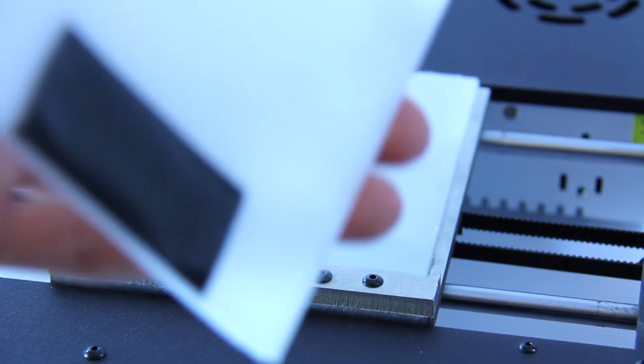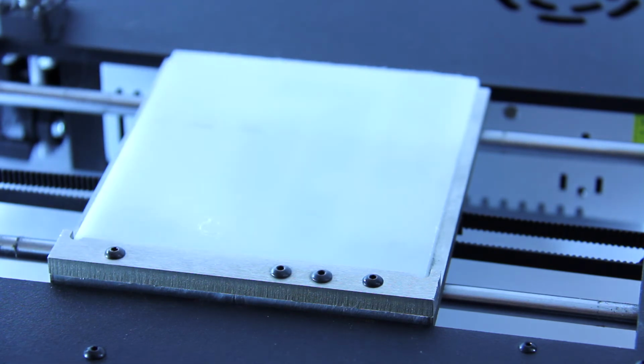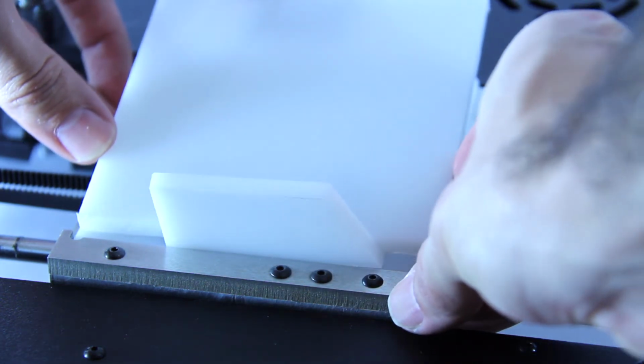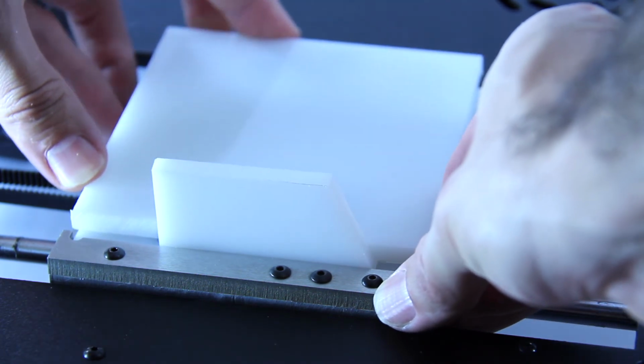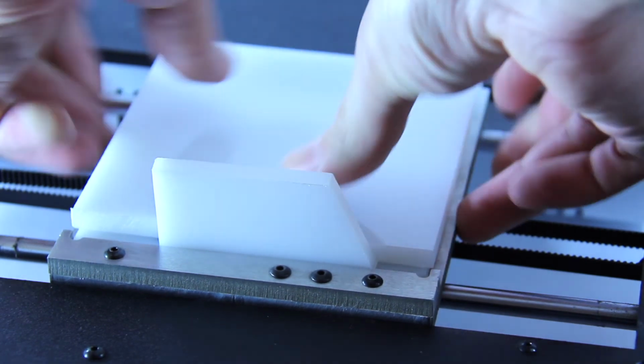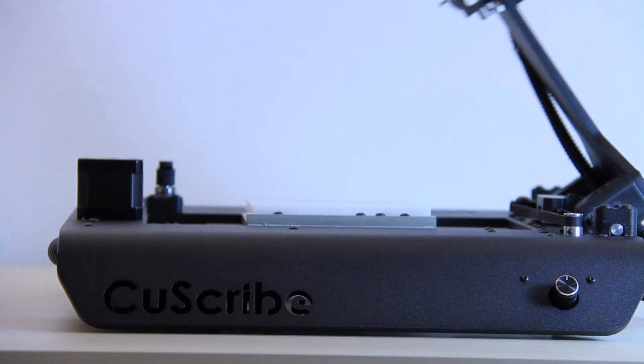Using double-sided mounting tape, we stick our material to the spoil board. To avoid getting the adhesive on the cutting tool, we place the tape in areas where we will not be milling through the entire board. We then stick the stock onto the spoil board. Offsetting it from the alignment bracket is done to ensure we don't accidentally cut into the bracket.